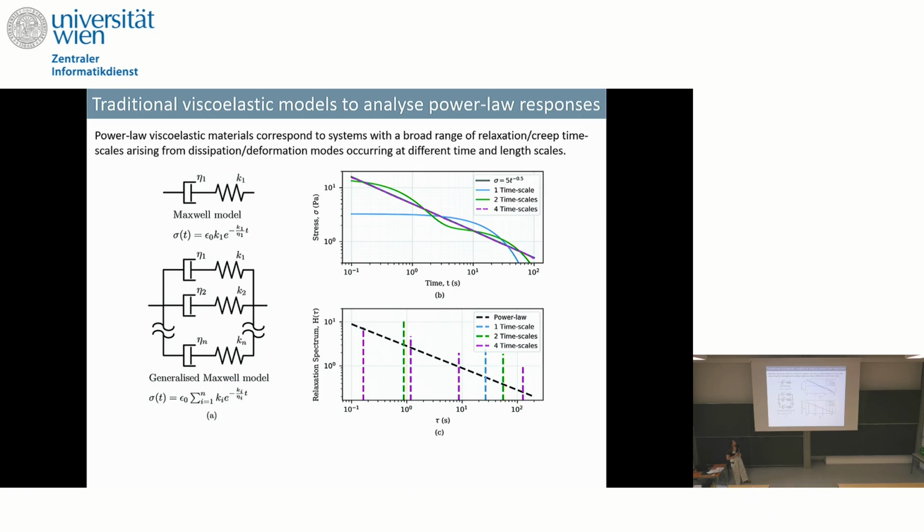Let's try to plot it with one Maxwell model. That's the blue line. It's not really doing a great job because we are just sampling one characteristic time. Okay, let's try with two. So we're sampling the spectrum with two characteristic times, better. The qualitative behavior is captured quite well. We've sampled in a log scale our spectrum and we have a nice fit.